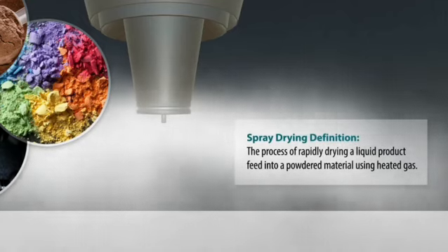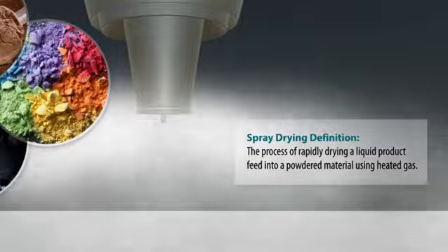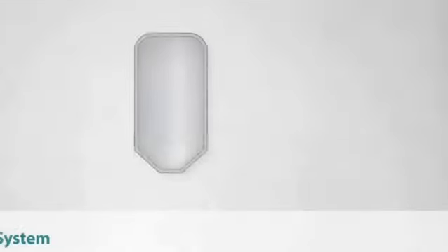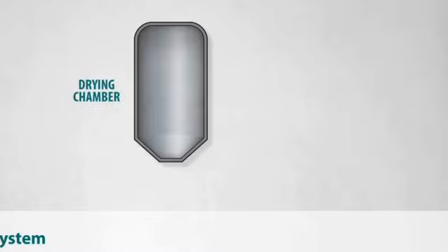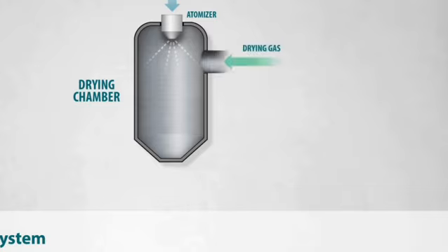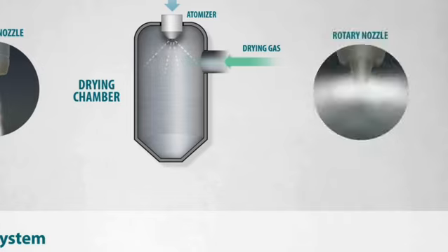Heat energy from the air evaporates water in the droplet, and the water vapor moves into the surrounding air, leaving dry, solid particles behind. Think of it like spraying a fine mist of water into a warm, dry room. These tiny droplets evaporate quickly, leaving no wet residue. Spray drying uses this principle, but in a controlled industrial setup, producing uniform, high-quality powders.